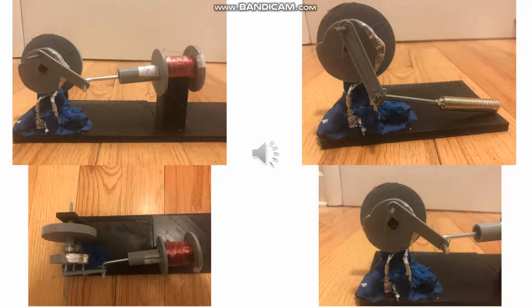The setup for our design consists of a wire coil wrapped around a hollow cylinder shell, with a small guide to hold the neodymium magnets in place and at the center of the wire coil. These are attached to a connecting rod, which connects the magnets to a crankshaft. The crankshaft has a flywheel attached to it, which allows for the mechanical energy to be stored, and a cam, which every half turn hits a switch.